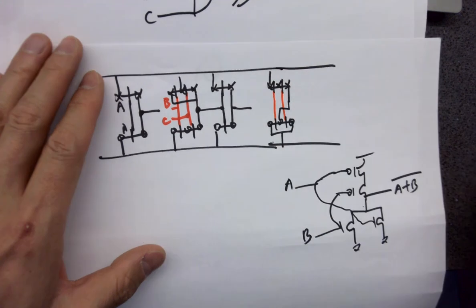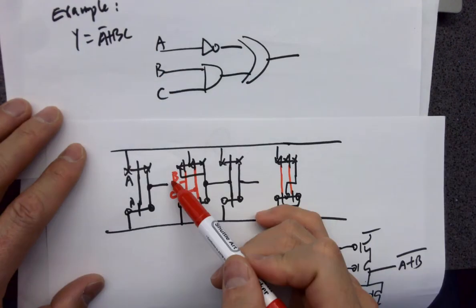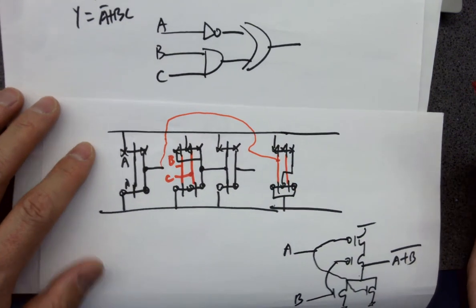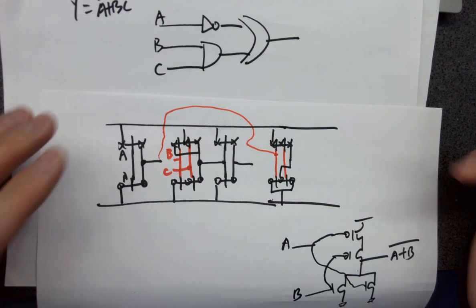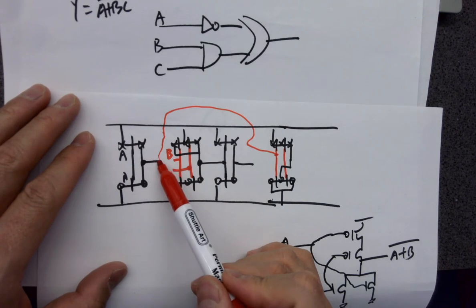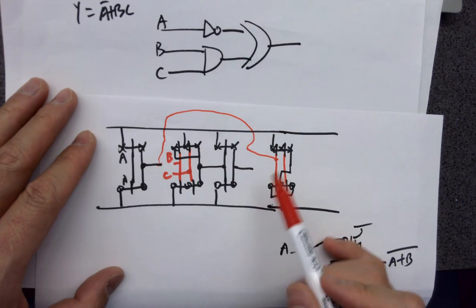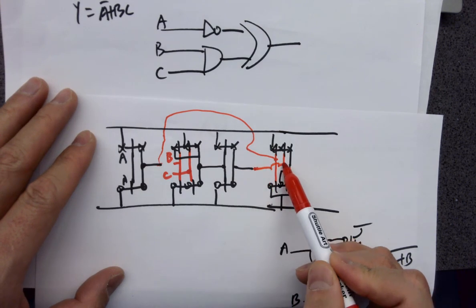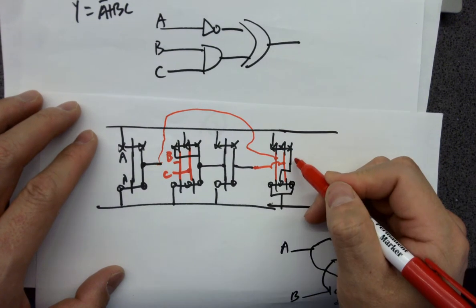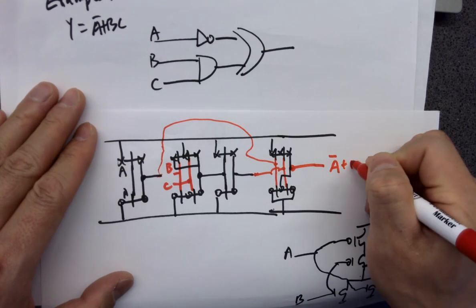That's a gate. It's taking output from the inverter, which is here. I know you are not going to do it that way, but just showing you the connection. Okay, there's nothing that can go beyond the power rail. Everything has to be within that power rail. I don't have a different color here. So the inverter's output goes to the input of the OR gate, and the AND gate's output goes to the another input of the OR gate. And here's the final output, which is A NOT or BC.